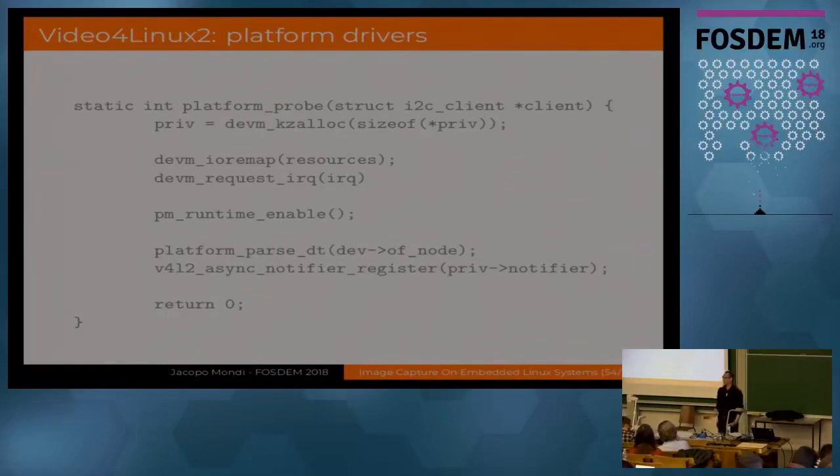So this is a typical probe sequence of a video capture driver, and you do the usual things: you allocate memory, you request interrupts, you deal with power management, and this is very platform specific, depending on what the hardware does. But there is a part that is quite common, which is the DT parsing part. During the DT parsing, you basically walk over your endpoints and collect the references that represent the sensor your SoC is connected to.